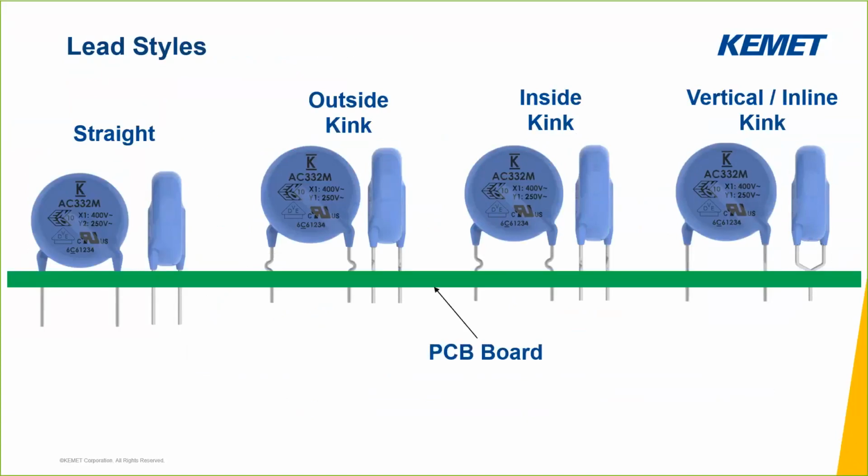Now, the various lead styles that are available provide different mounting options. The straight leads will seat all the way down to the lower portion of the disc. This means that the capacitor will either touch the PCB or the assembler must hold it above the board while soldering, which can lead to inconsistent mounting heights. When choosing a kinked lead style, the capacitors can seat on the circuit board at a consistent height without the bottom of the disc touching the PCB. Each kink lead style, whether outside, inside, or vertical, provides that benefit.